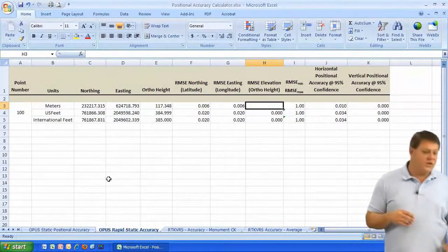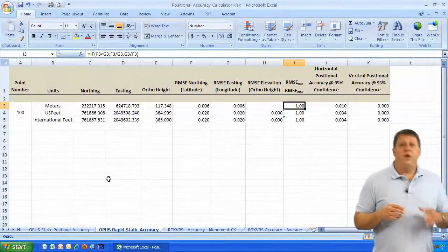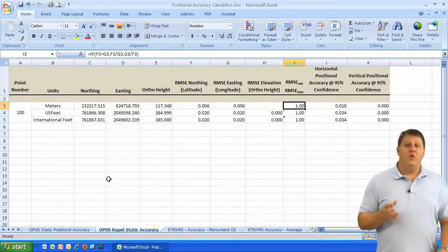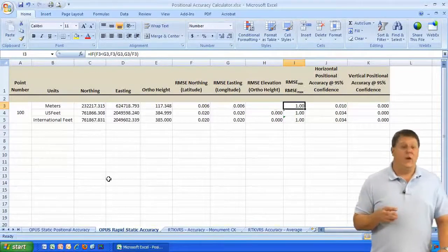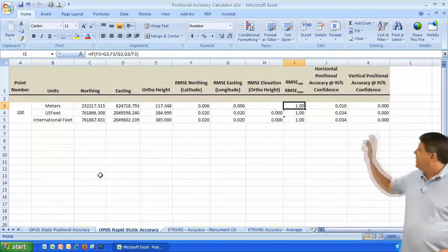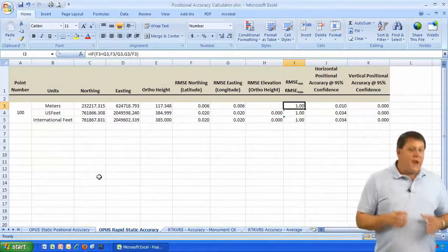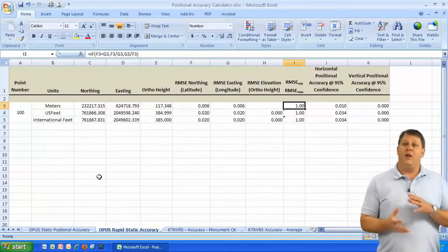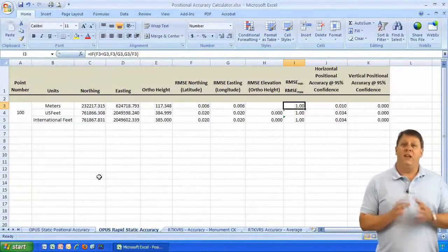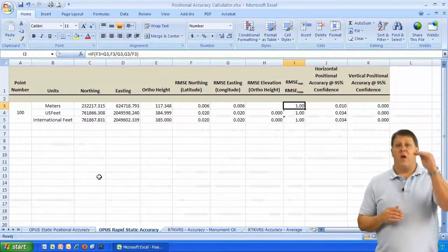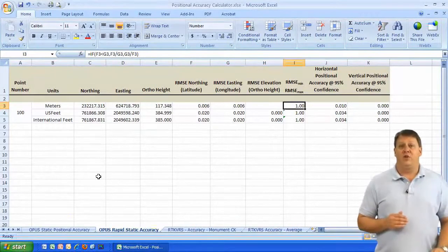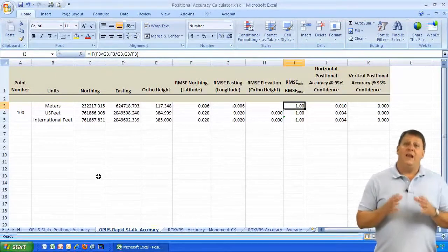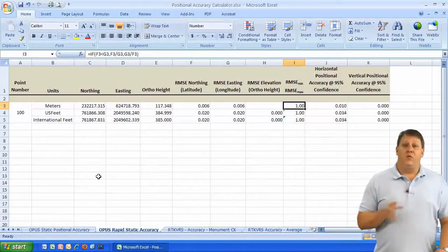And that's what the spreadsheet has done. If we go over to the min-max column for root mean square error, we can see there's an if statement running here. It's trying to figure out whether one value is greater than another value, and if so, it takes the smallest value and divides it by the largest value. If not, it gives us an answer of 1.